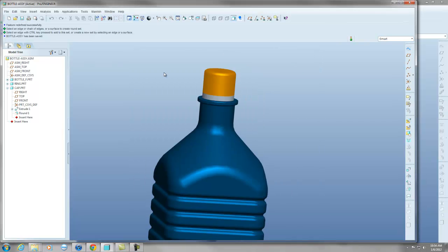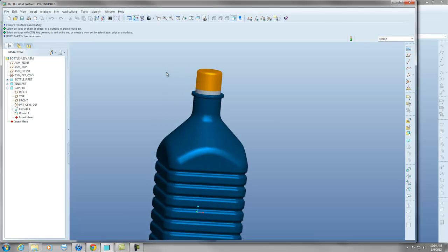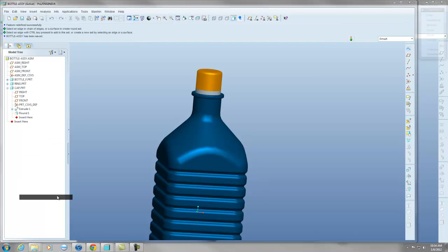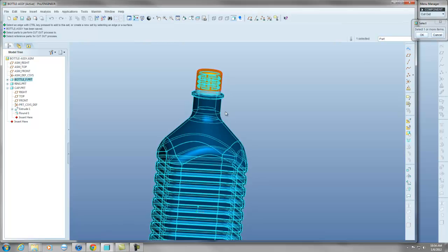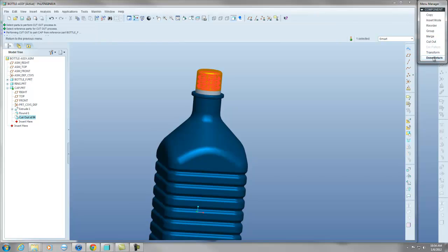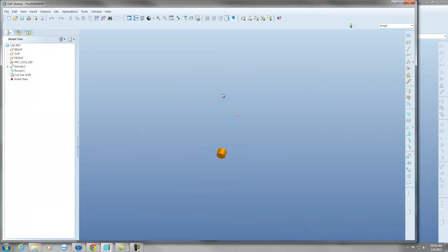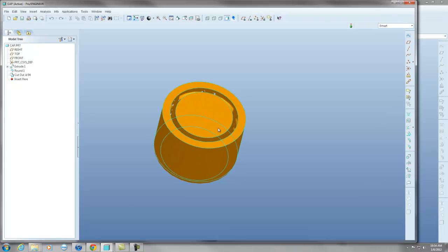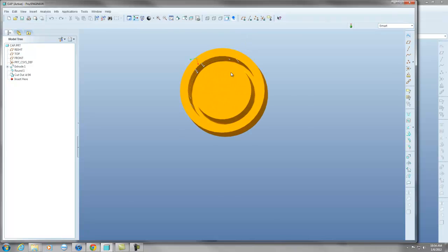So what you could do to do it quickly, let's see if it'll work. Component operations: go to edit, component operations, cutout. Select your cap first, hit enter. Select your bottle second, hit OK, hit done, hit done return. Now when you open your cap, you will see that your teeth are in there. Dang it.